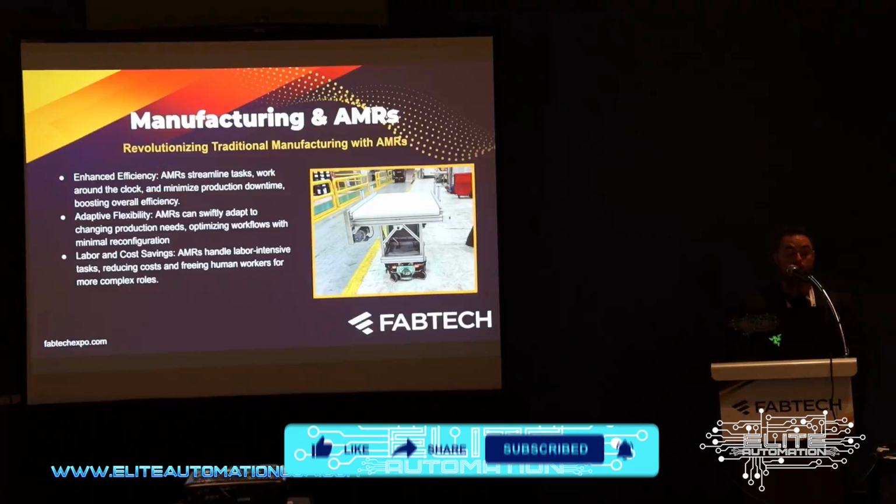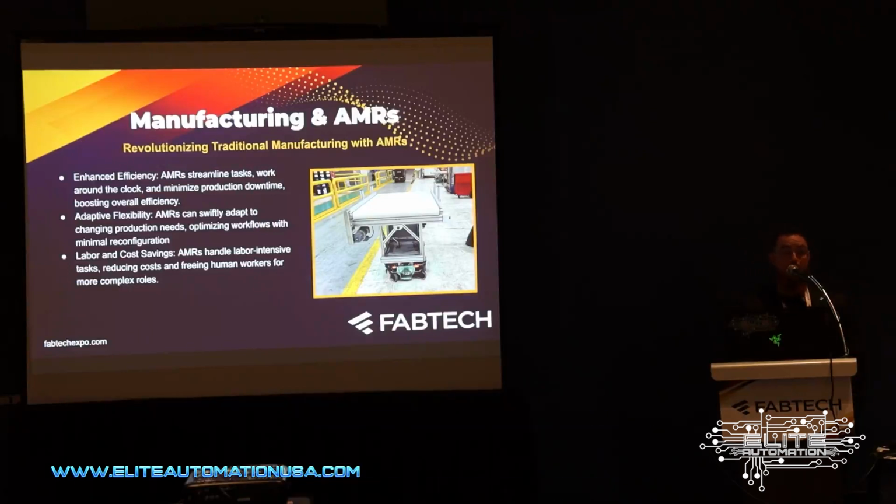You could highly reduce your labor costs with fork truck drivers, even if you don't do full completion. Let's say, for instance, you have an operation where you're taking a full pallet and driving it all the way to the end destination of a semi-truck, right? Maybe the AMR is not the best solution to actually drive up into the semi-truck and drop off the package. However, the AMR can handle the heavy workload and carry it all the way from the finished product area to the loading dock, where a fork truck driver then does the final loading of the product.